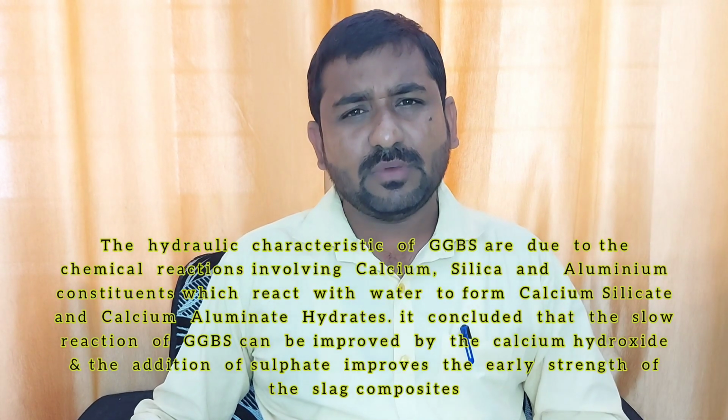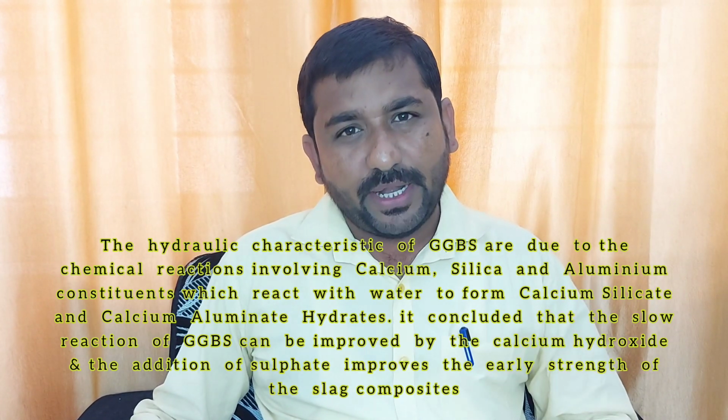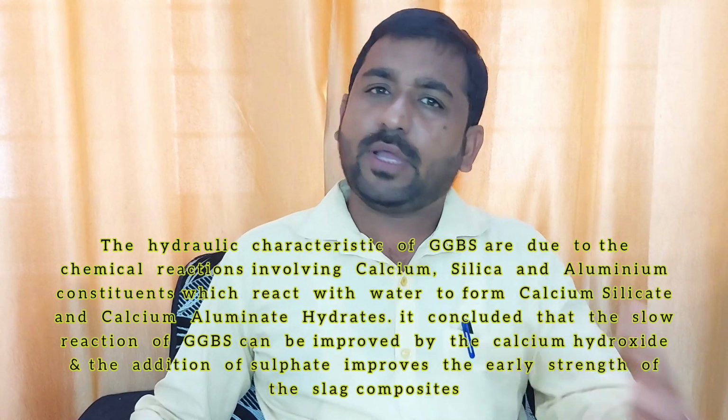The glassy phase consists of alumino-silicates of calcium, which is mainly responsible for the hydraulic, cementitious properties of GGBS. To activate that alumino-silicate of calcium, we require alkali activators, in the form of calcium or additional silicates, which can be provided in the form of OPC, or you can provide them additionally.